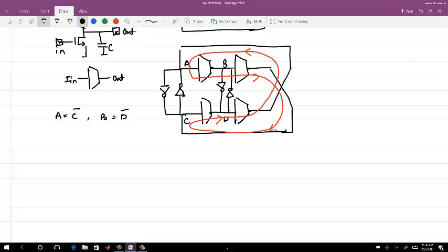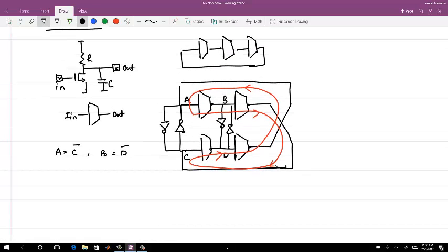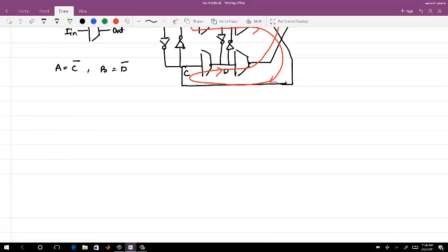Okay, and since we are using this particular cell as a basic cell where transistors are in saturation and your gain is gm times Vin into the load impedance. So in this case, let me say, if you do not consider any cross-coupled inverters in the system, you have the gain as we worked out yesterday.